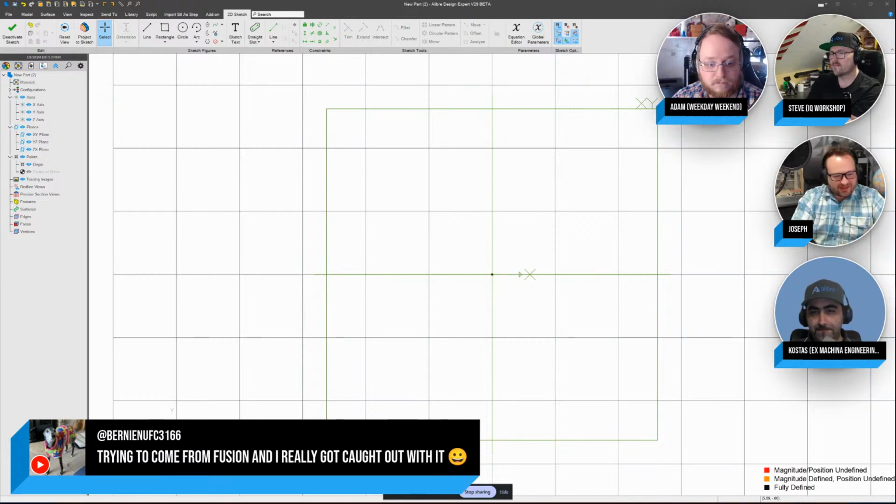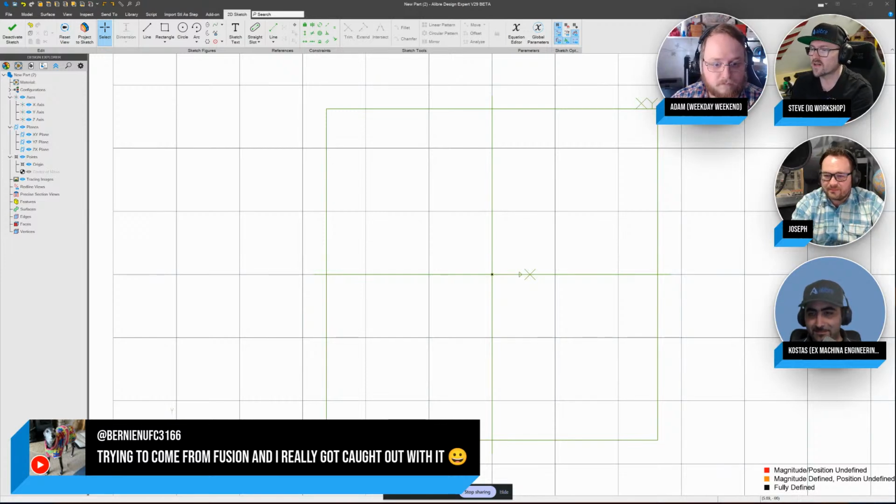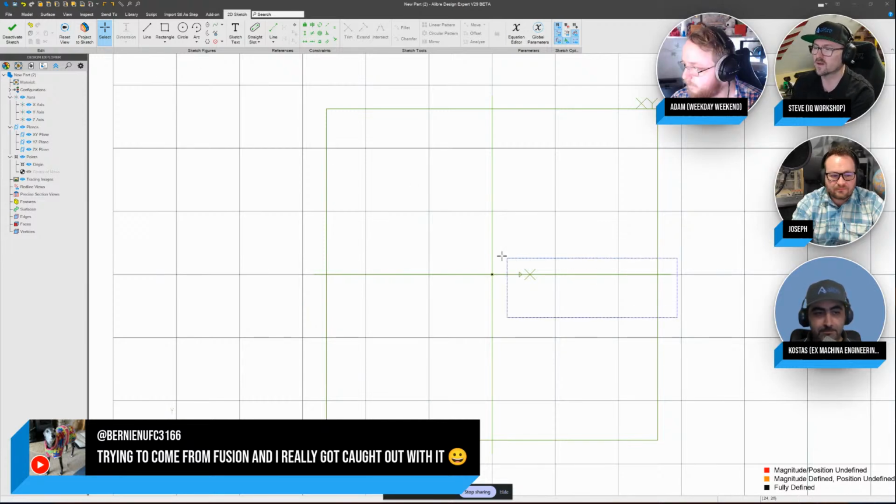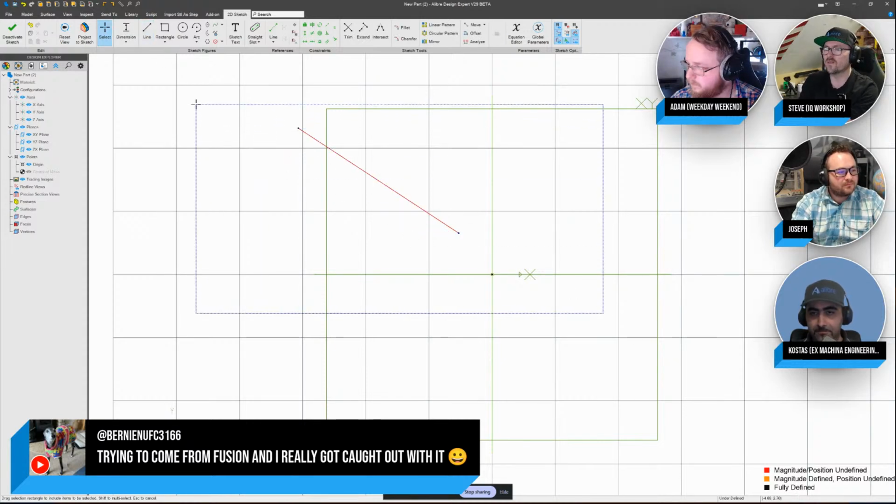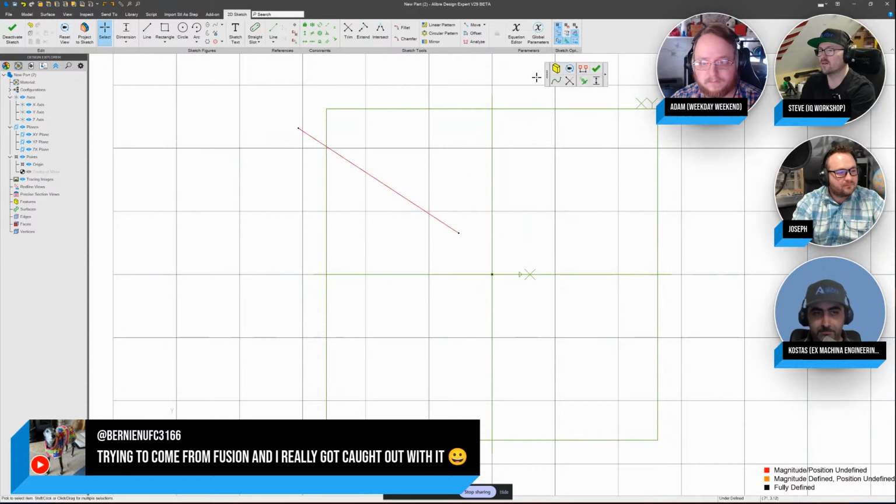I'm changing the subject again, back to that click and drag rectangle. I wanna look into that and see what we can do. Sounds really nice, actually. There's a few other selection options, and I'm potentially going to expose my lack of knowledge here, but clicking and dragging in one direction versus another direction when you're selecting things can often yield a different result. So if you click and drag left, you can select a single line that's within the selection box. But if you click and drag right, it selects anything touching the selection box.